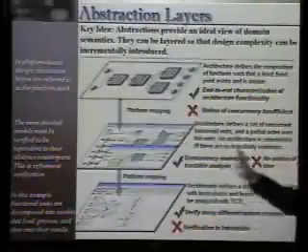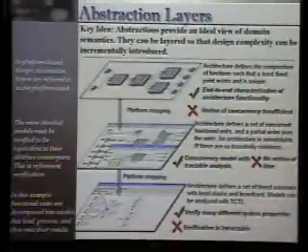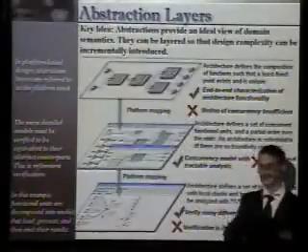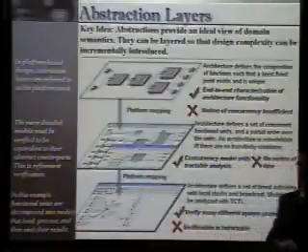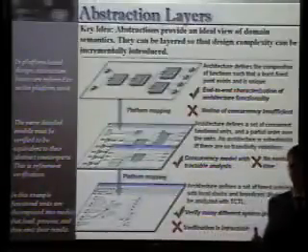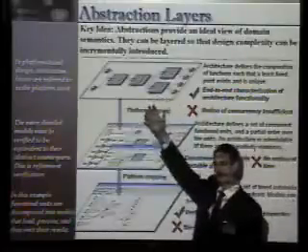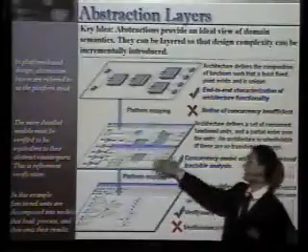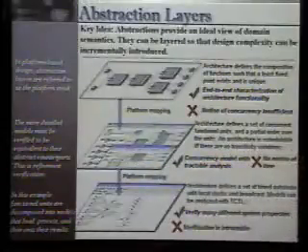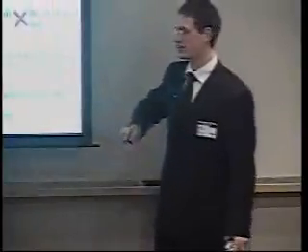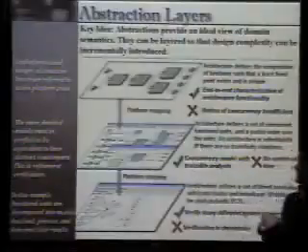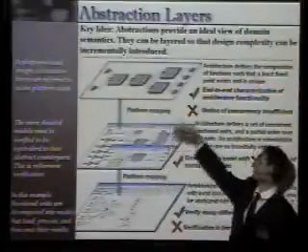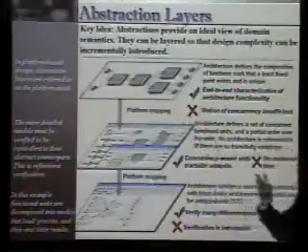But now it comes time to say that these blocks, for example, are concurrent. They can run concurrently. And this model here doesn't capture that concurrency. So what you do is you build another domain-specific language, let's say something based on synchronous data flow graphs, where you map this less detailed architectural model onto this more detailed synchronous data flow graph that now talks about concurrency. And once you do that, you can ask some interesting questions. Does there exist any deadlock, for example, in the system? You can do deadlock analysis here. Where up here, it didn't make any sense to do deadlock analysis because the semantics were too simple.